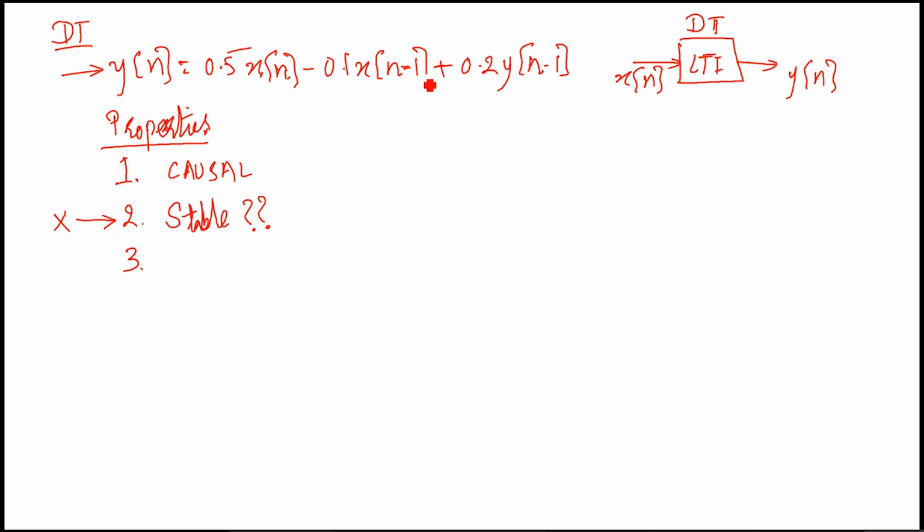Okay, I think you are feeling shy about it. So this is not an FIR. This is IIR, because there is a y of n minus 1 term. You see, if we had just feed forward terms, then it would have been FIR. To compute the output, if we only required feed forward terms, it would have been FIR. But here we have this feedback term, y of n minus something. If you have even a single feedback term, that makes your system IIR.